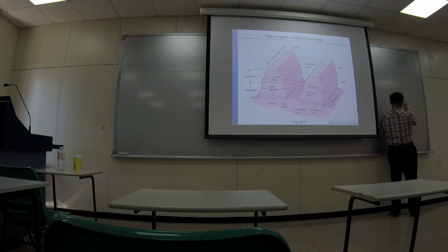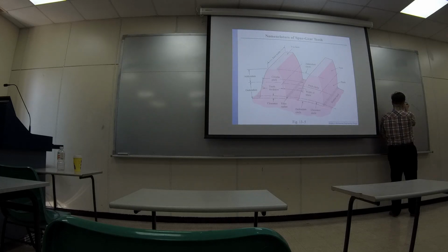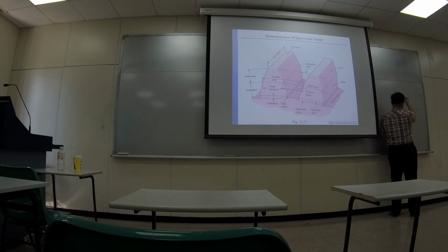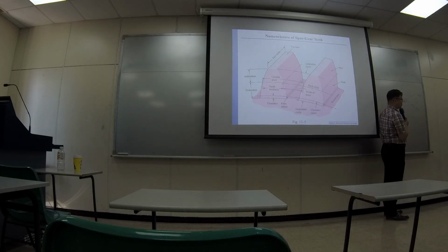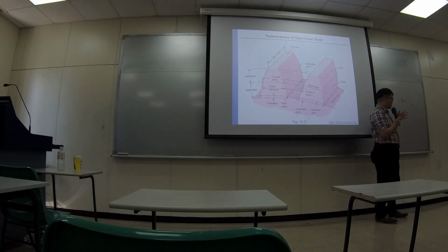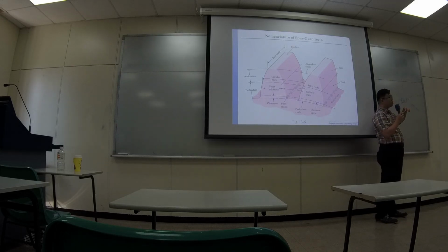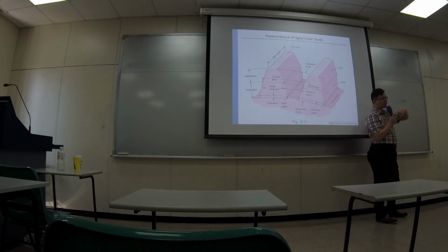So let's say when the gear moves to the other configuration, for example, this configuration, and the other side will have a different motion like this, and the contact point remains on the same line. So this force transmission stays in a very stable direction all the way when two teeth conjugate with each other.